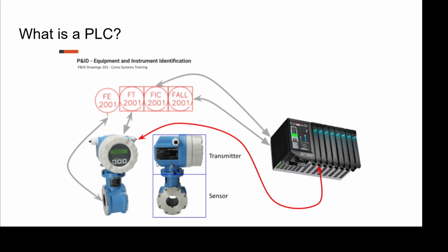So that's fairly complex if you're just looking at this for the first time. But effectively, you would specify what type of, in this case, what type of flow am I measuring? Is it water? Is it a gas? Is it like oil or gasoline or something? That would determine what type of sensor type we need. Then we would specify various ranges and things for, say, it needs to read from 0 to 10,000 gallons per minute or 0 to 100.